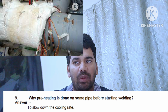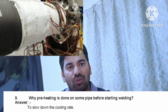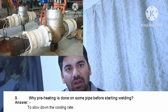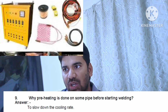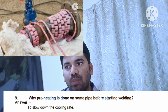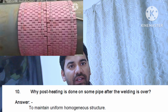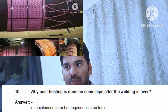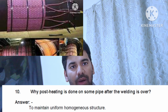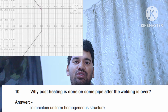Okay, the next question is why preheating is done on some pipes before starting welding: to slow down the cooling rate. Preheating means that when you do the welding, you need to control your cooling rate. Why is post heating done on some pipes after the welding is completed? Post heating is done to maintain a uniform, homogeneous structure. That's why post heating is done.